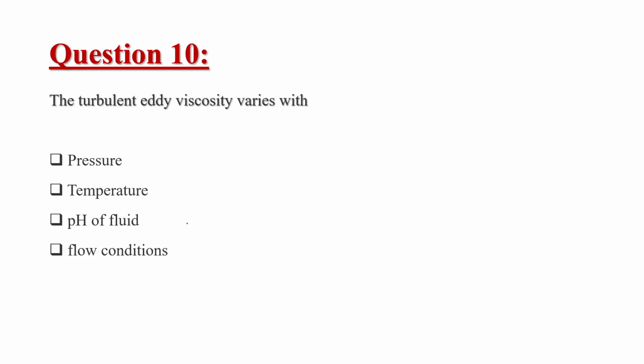So we have to find this mean velocity by substituting the value of u from here into this equation. That means here we have 1 by h into integration from 0 to h, and this we can write as a into (h minus y) into y into dy. Right? Correct? That means, if we write 1 by h, we can take a as common. So here we will be having a into y, so if we integrate it, it will be h into y square by 2, minus, here we are having y square, so if we integrate it, it will be y cube by 3, and this has a limit from 0 to h.